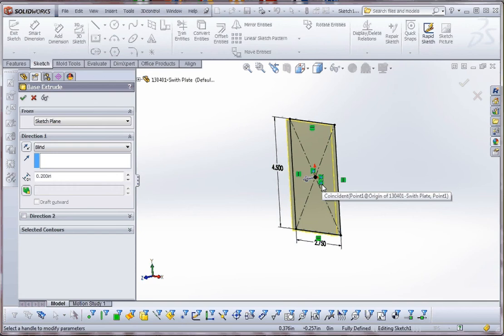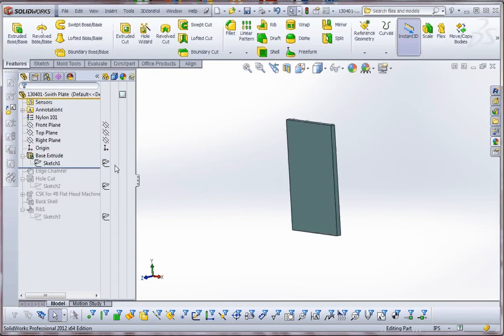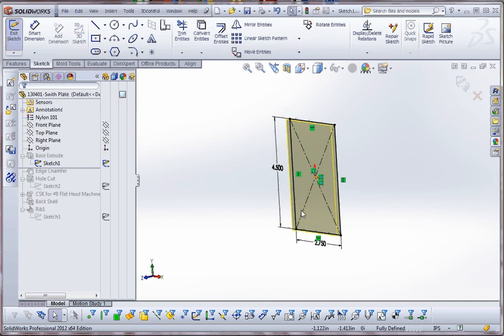But in this respect, if you think about the plane of the wall, where the drywall is, and the plane on top of that, you can consider that as also being the front plane, and we're actually extruding that switch plate from that plane. So we're going to go out 0.2 inches blind in that one direction, which is coming out towards us in the z-axis. You can see that down here. So that's our base. And if we go back to that sketch too, you can see that we've just done the basic sketch here for that particular feature.